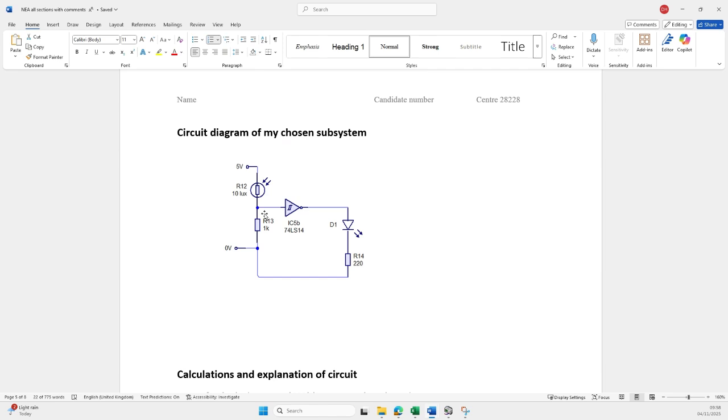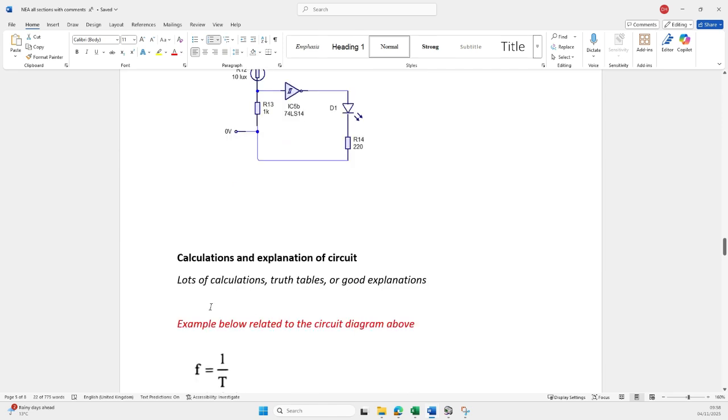You might say that it should be powered from a 5-volt power supply, and you could say that it should interface with a latch, for example. Obviously, the interface with a latch bit you would have to check later on, but you could still say, because it turns the LED on, that will provide enough current to latch or unlatch as well, because you've got at least 20 milliamps of current available. So you could say something like that.